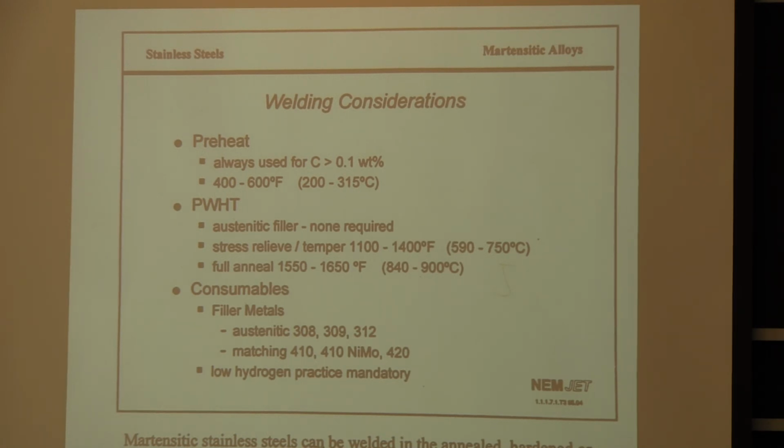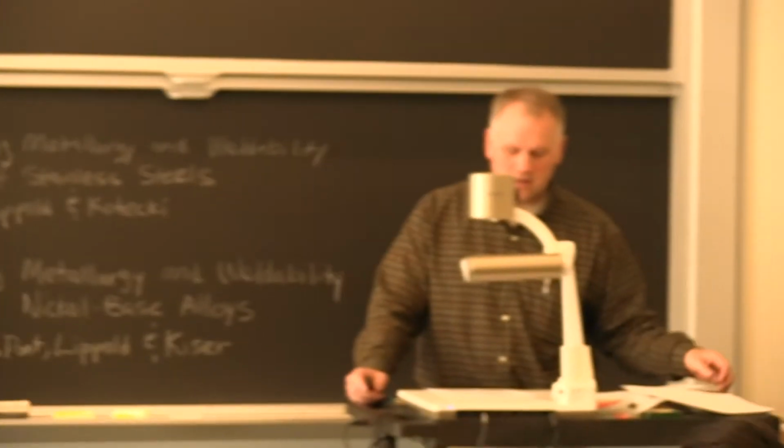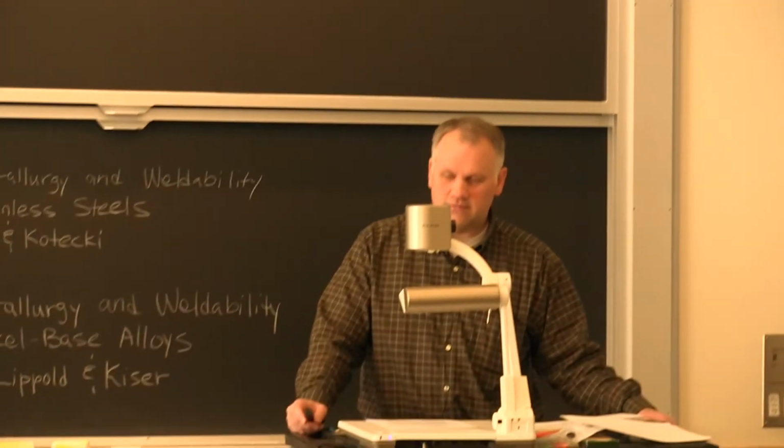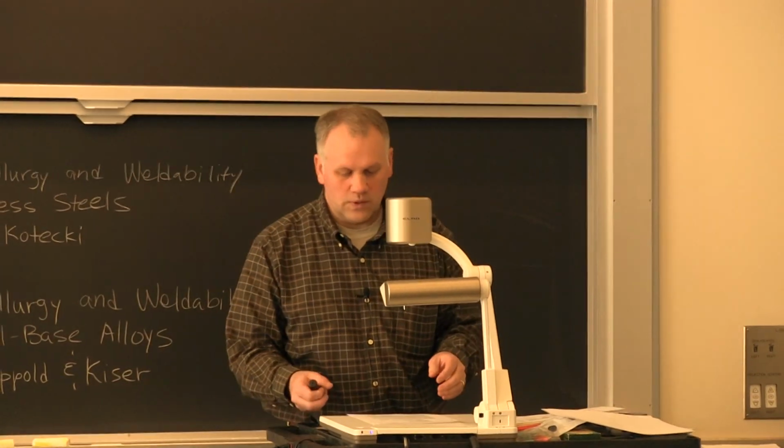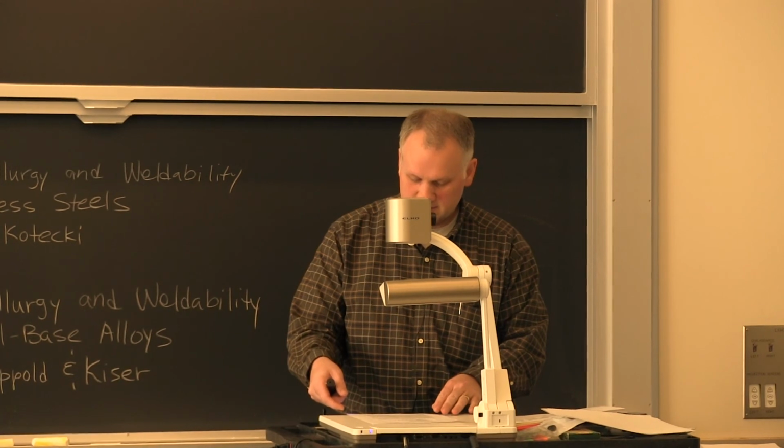Also, just for the hydrogen issues, and it sounds like Professor Eager will touch on that even more tomorrow, but low hydrogen practice when you're welding these, which includes cleanliness, and using gases that are clean and low hydrogen. It uses filler materials that are low hydrogen. That's all mandatory when you're welding on martensitic alloys.